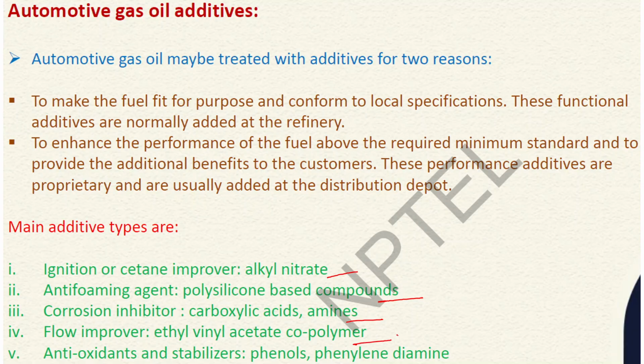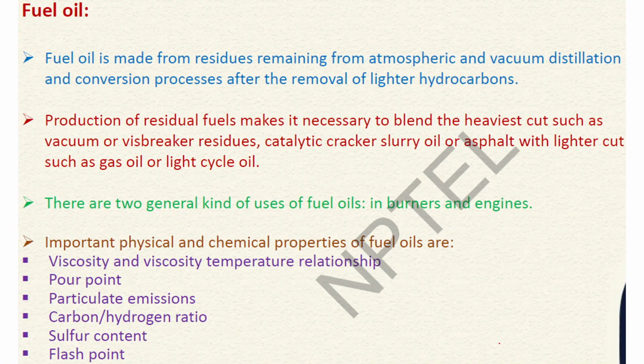Then flow improvers, to prevent the formation of wax inside the diesel fuel and to improve its flowability from a hot region to a cold region. Then antioxidants and stabilizers to prevent oxidation and to provide oxidation stability to the gas oil.